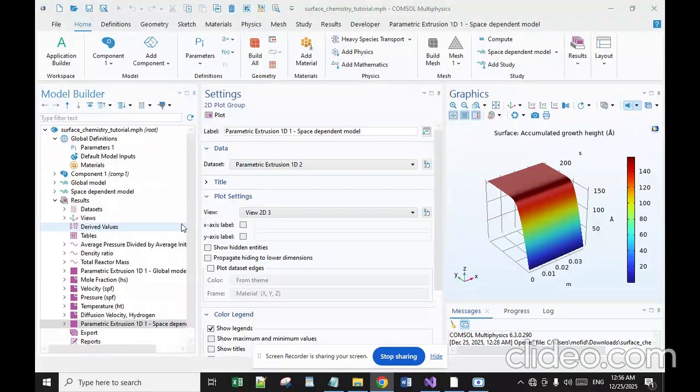However, silane produces a lower quality oxide than the other methods, with lower dielectric strength, for instance, and it deposits non-conformally. Any of these reactions may be used in LPCVD, but the silane reaction is also done in APCVD.